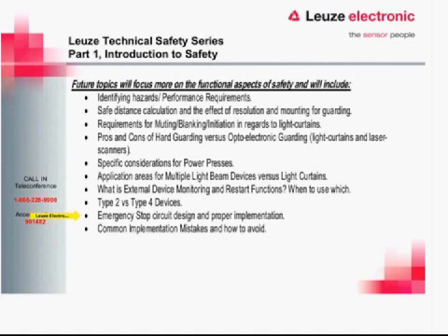We see a lot of e-stop circuits in the field that are not being used correctly. So this is something important that we need to get down, because the e-stop is not like a light curtain. It's not restricting a dangerous movement. It's not restricting access. This is, in truth, an emergency stop. Everything needs to stop.